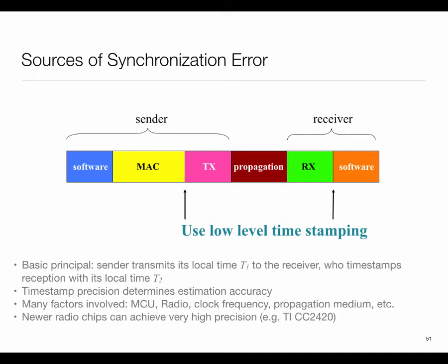The chips that you get usually have some sort of signal that says, hey, I'm actually transmitting now, or hey, I have now received the packet. The trick is that they monitor the same location in the packet, and you want to make sure that it's the same location. Usually it is where the header ends and the payload begins, so they mark that boundary. You will see signals like start of frame delimiter or end of frame delimiter. These signals basically say, I've recognized the header and the payload is starting to be sent now, or I got the header and I'm now receiving the payload. That's the kind of pin they would often give off. Radios seek to support good timing.